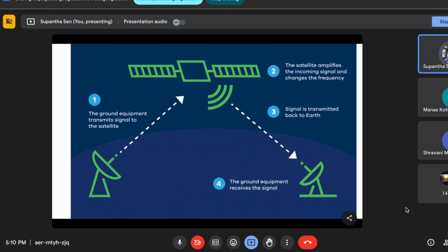Those kinds of satellites are called communication satellites. In a communication satellite, you have a receiving antenna, you have a transmitting antenna, and in between you have a repeater, which does some filtering of the signal. They will not change the signal, they will retransmit it with some new power. That is called a transponder. That's why those payloads are called transponders.